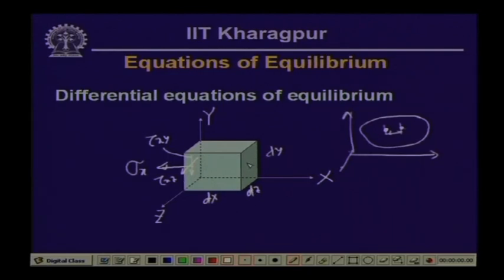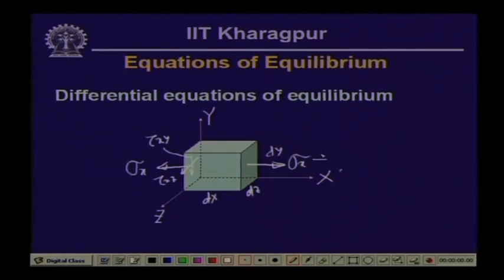The normal stress acting on this plane will have the component sigma x plus del sigma x by del x times dx, acting over the length dx.